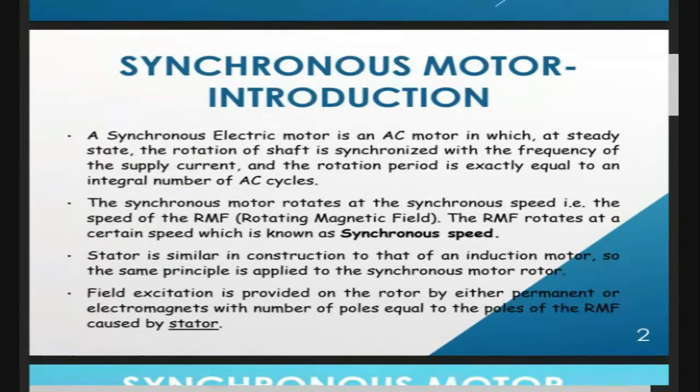Now, because of the rotating magnetic field, we experience that the magnetic field is rotating, revolving, and our rotor circuit is excited, or we can say it is given a supply with a DC supply. Okay, now what is a speciality of DC supply? That it has the same polarity. So the same polarity means the magnetic field which is created will be constant.